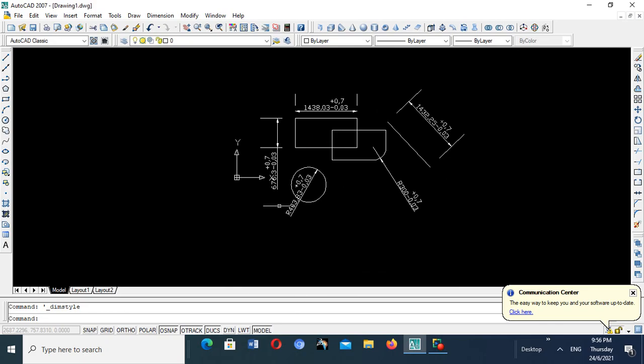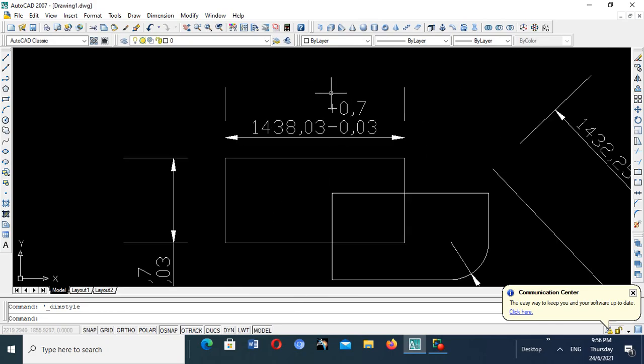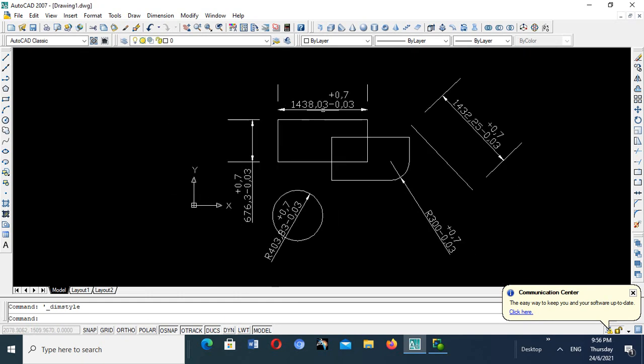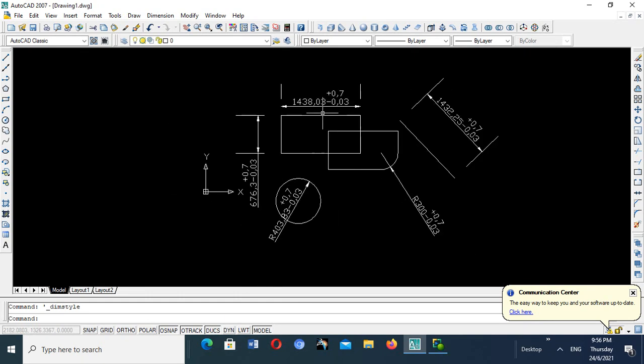So with this, we want you to practice how you can optimize your drawing by making sure you change the parameters that affect the sizes of your dimensions in terms of text height, arrowhead type, distance of the dimension line from the end, and so forth.